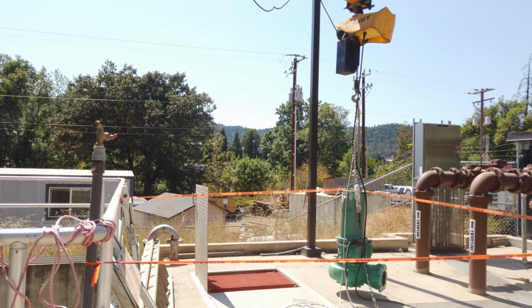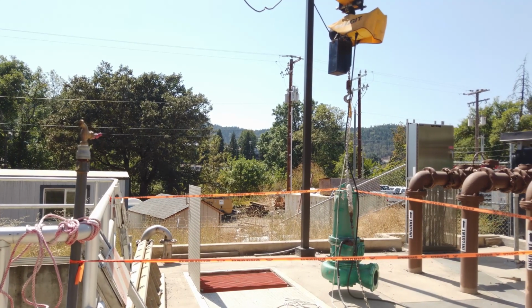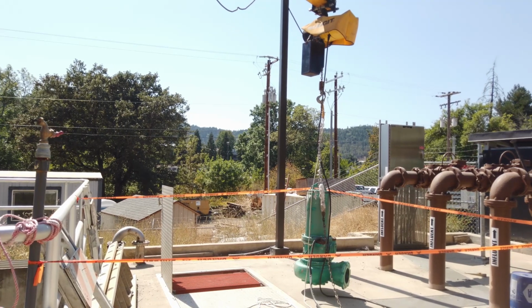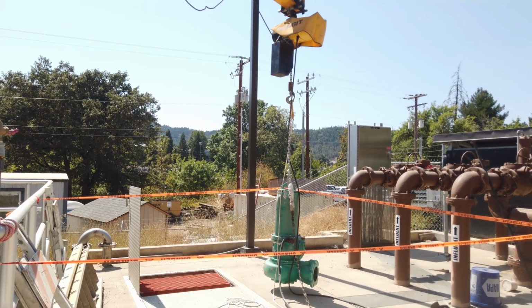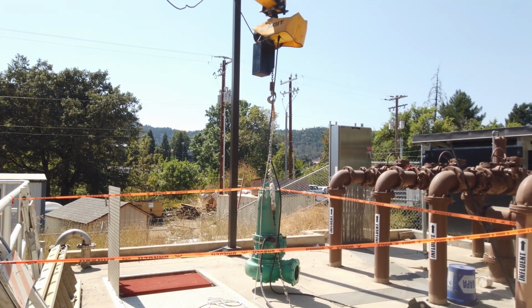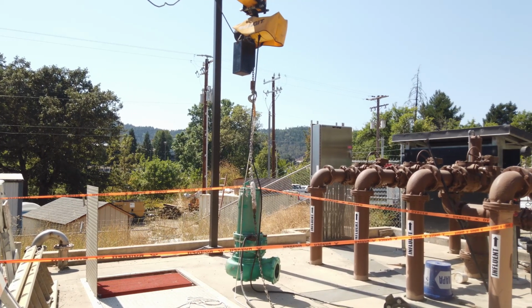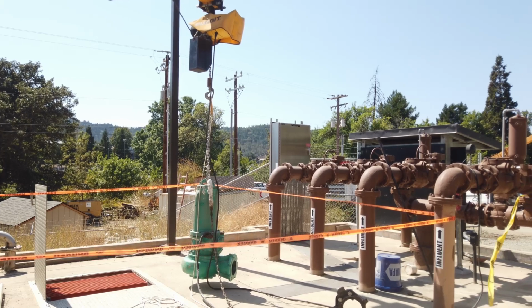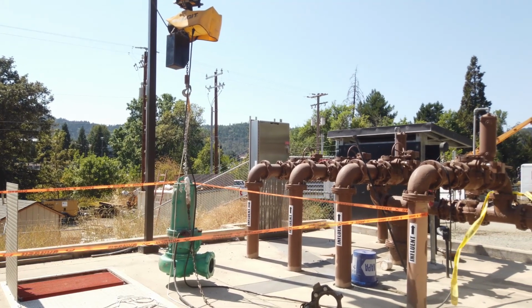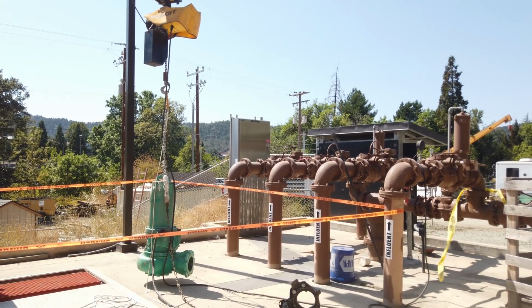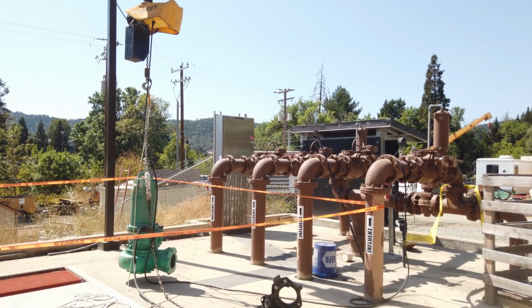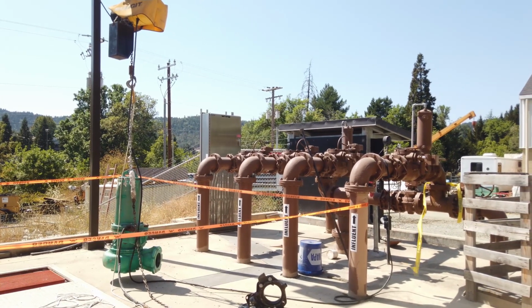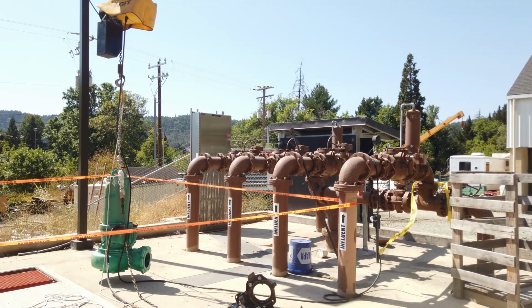This is the influent pump station. Influent wastewater is conveyed to a wet well that houses 4 pumps, 2 jockey pumps, and 2 large pumps. The jockey pumps manage influent flows throughout most of the year, typically outside of storm events due to infiltration and inflow. The influent pump station was constructed as part of Phase 1 improvements and pumps to a new secondary screen, which is part of the main wastewater improvements that are currently underway.